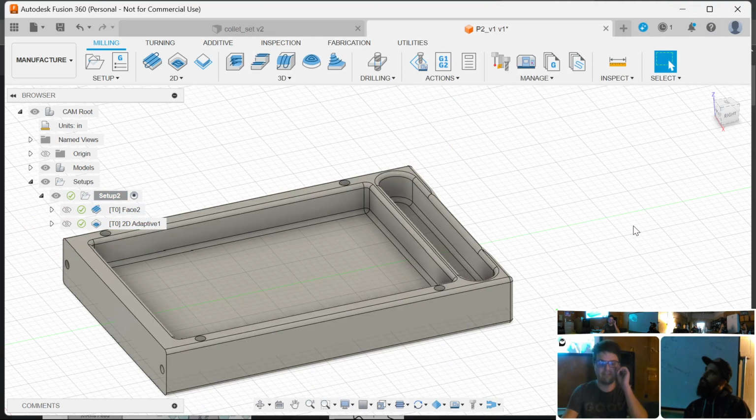Fusion 360's free version is very, very powerful, but tries to waste your time as much as possible. One of the things that the free version will refuse to do is generate a single G-code file with multiple tools in it. It forces you to generate them in separate G-code files. Fine, whatever. You just generate 3 files, you copy and paste them over. It does mean that you have to separately load each file and hit run each time. Doesn't matter because we don't have automatic tool changers, so you had to change the tool manually anyway. Doesn't hurt us, does hurt production shops.